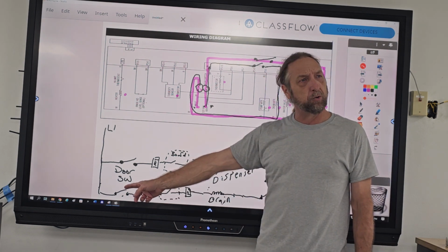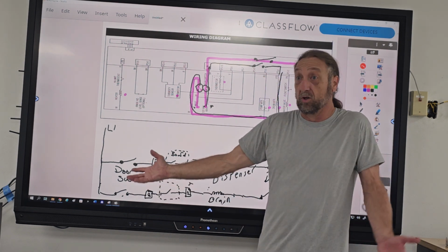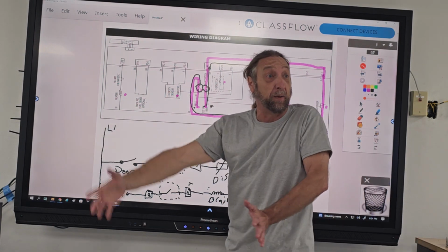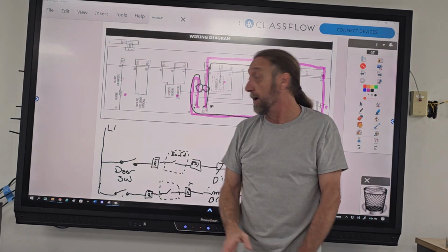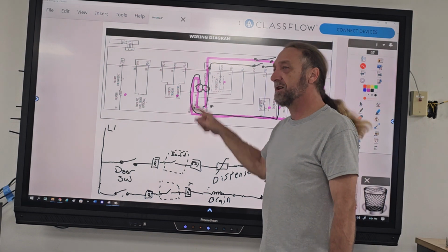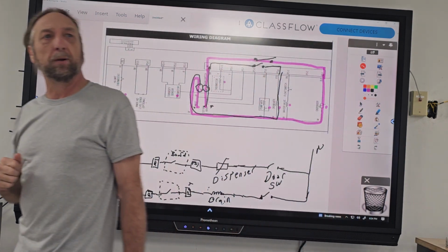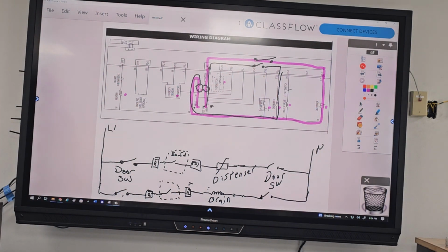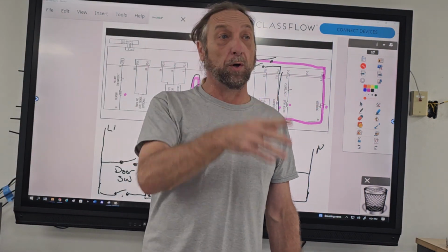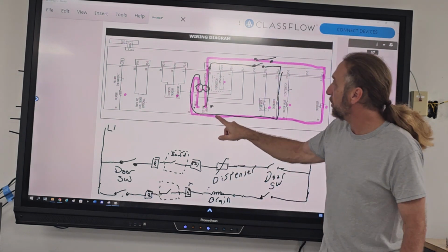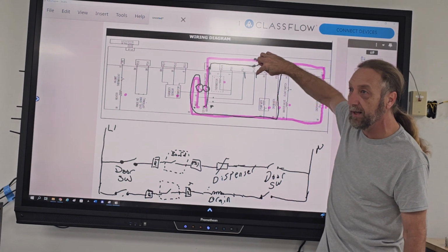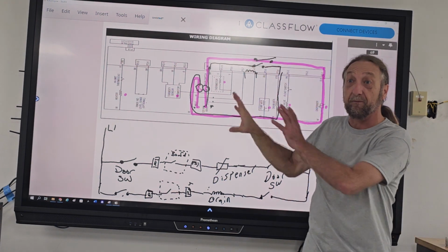So what does that mean about my door switch? It's good. It's the same switch for the drain pump as the dispenser, the water valve, and the wash motor. They all go through that switch. So if that switch was to fail, what do you think the customer's complaint would be? The unit not working. It would light up, but it wouldn't work. And the only reason I say that is you got another black and white wire from line 1 to neutral running to the board independently. These two are the transformer that feeds the whole board.